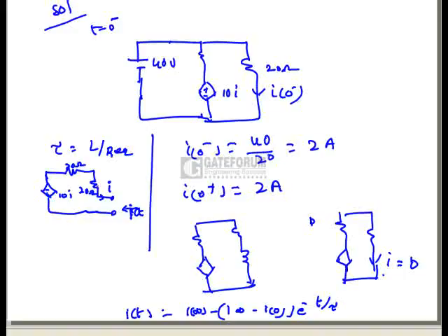So if you observe a KVL here, or I can say one method is, if you apply a voltage from this terminal and find out the current I, then V by I is nothing but an impedance, because suppose an unknown network is given to you. This is an unknown network, right? Now these are the two terminals of an unknown network. How to find out the resistance or impedance of this network, because we don't know what is inside the network?